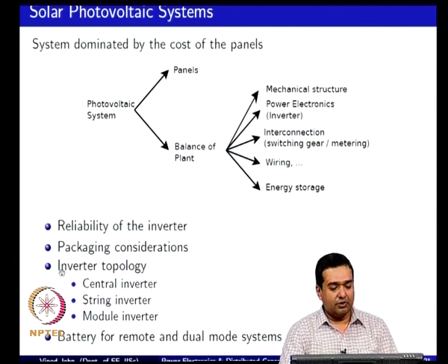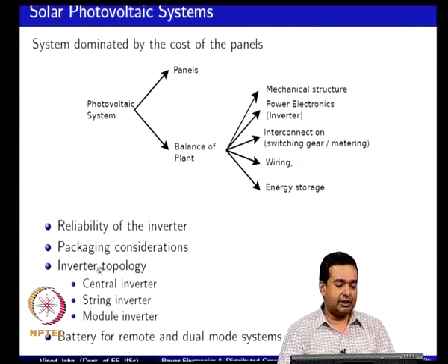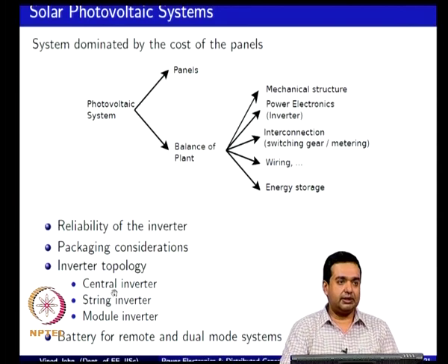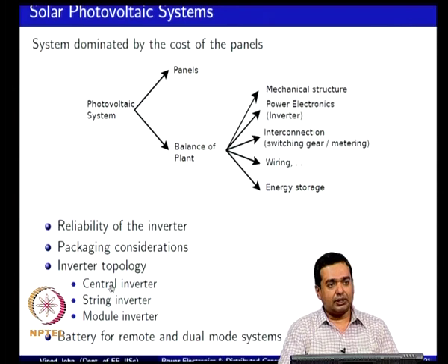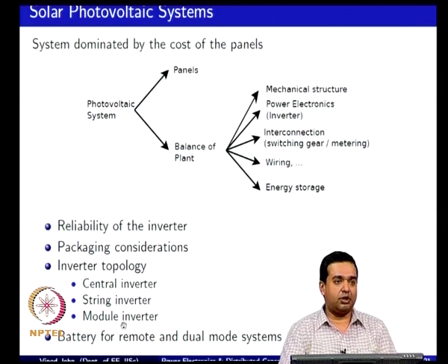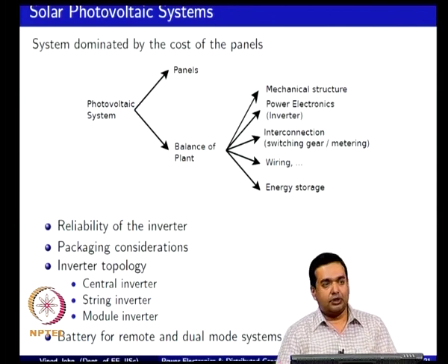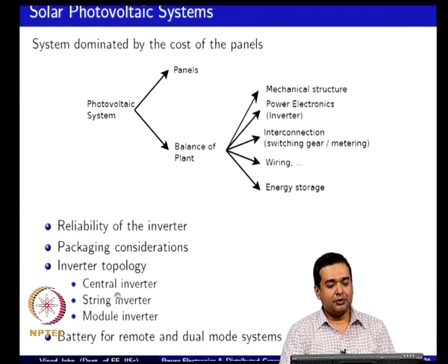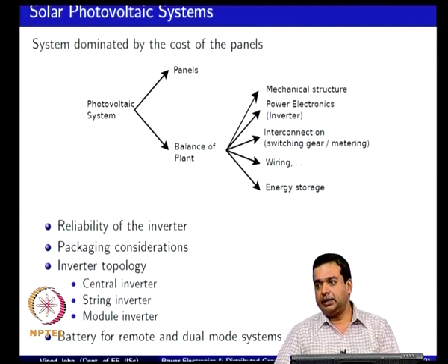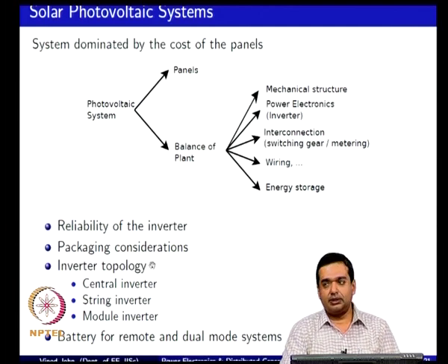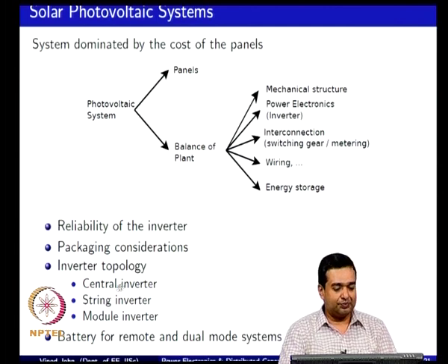An important part of the inverter is also packaging consideration. For example, if you have a solar inverter which is sitting indoors, the thermal issues are relatively mild compared to a solar inverter which you want to mount along with your module outdoors, or if the entire central inverter has to sit outdoors, you have to package it in a manner which will handle the heat, the dust, humidity, etc. outside, which makes thermal management more challenging. It can in turn affect the reliability. So, packaging consideration of the inverter is also an important issue.